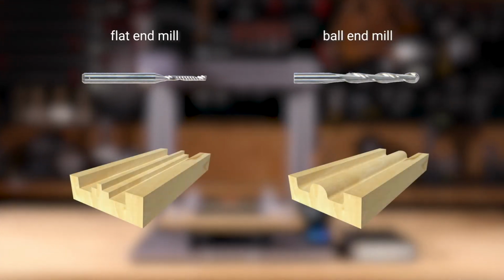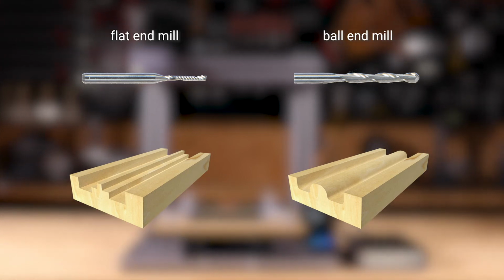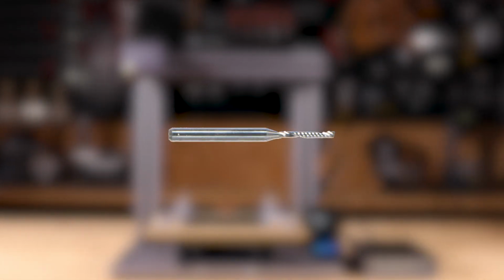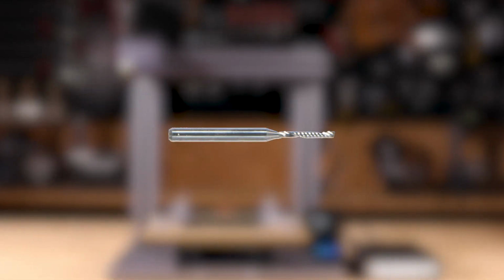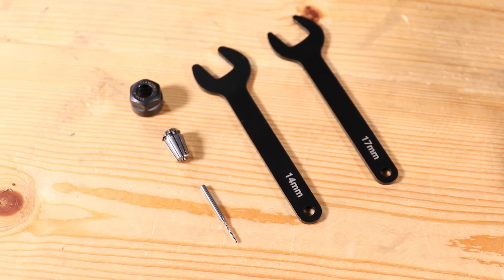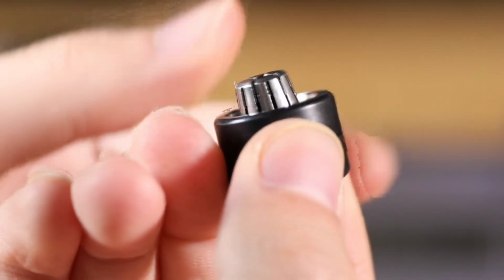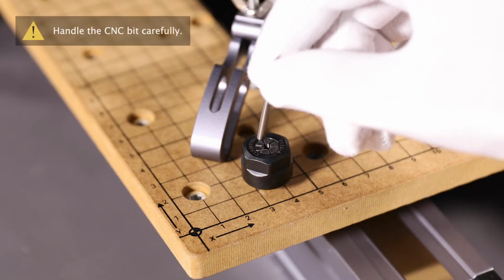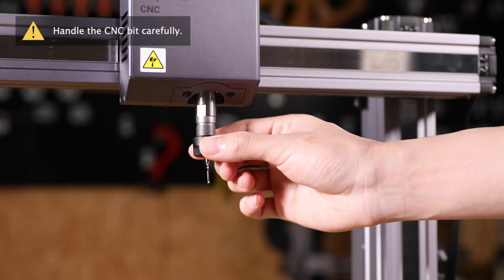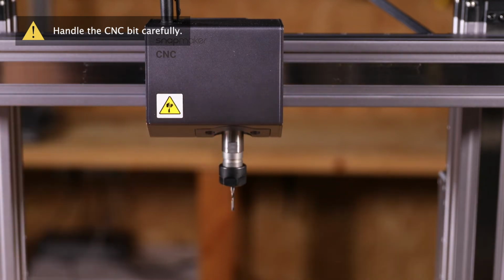Next, choose and install the CNC bit. Flat end mill is typically used for slotting or cutting materials with flat surfaces, while ball end mill is for carving materials into curved shapes. Since we are using acrylic cutting as an example, flat end mill is the better choice. So, take out the presented accessories and tools. Insert the ER11 nut into the ER11 collet until you hear a click. Next, put the CNC bit into the nut. Screw the entire unit onto the shank and tighten the ER11 nut using the wrenches.